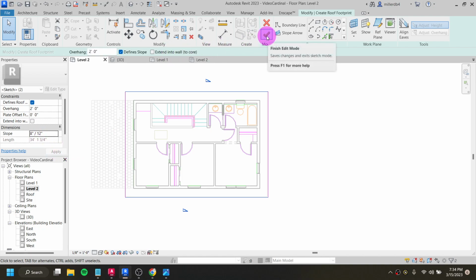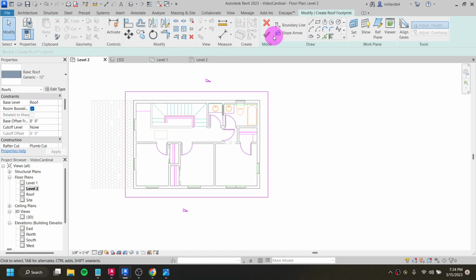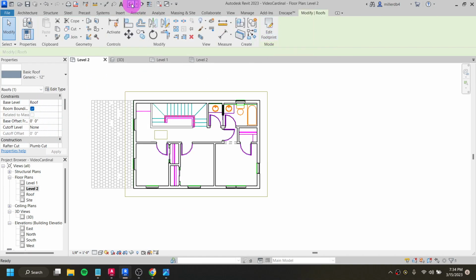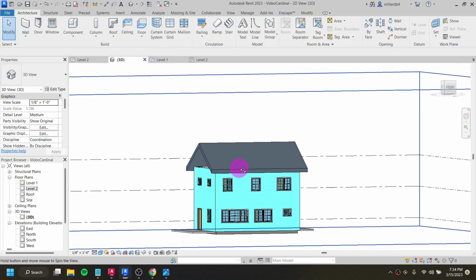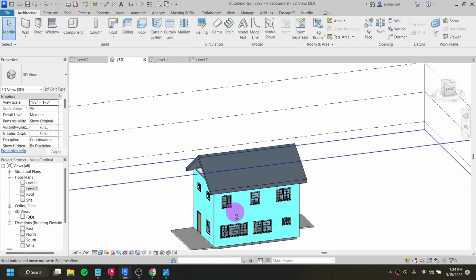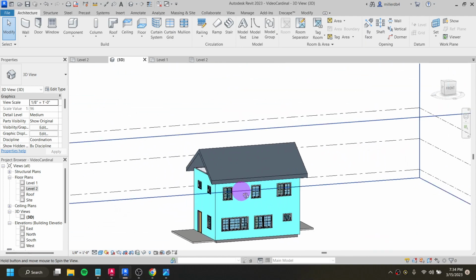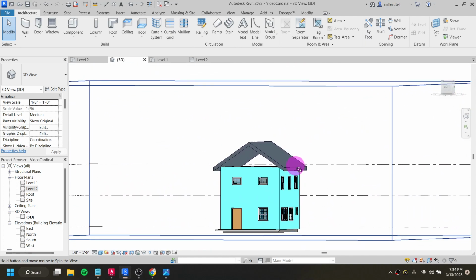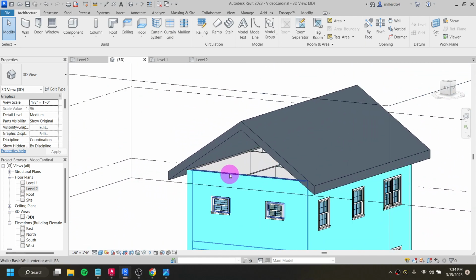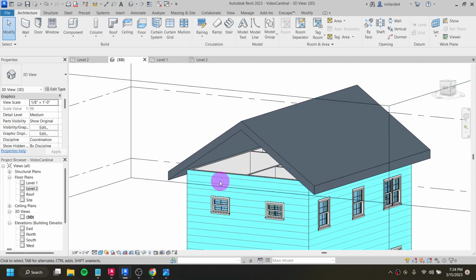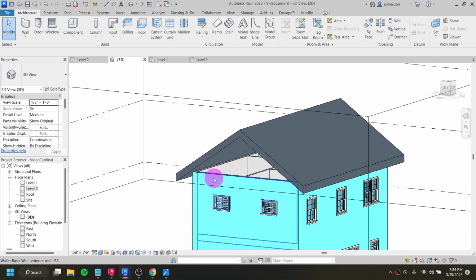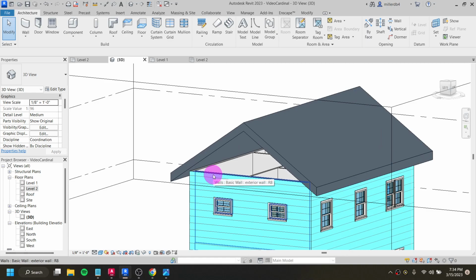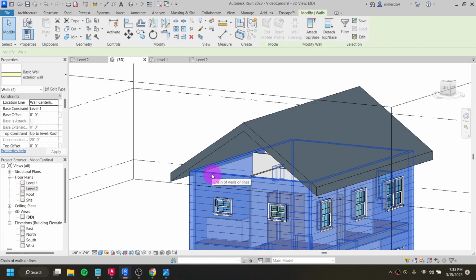Then let me just make sure that, okay, good, I've got my base level set to roof. I'll click OK, and I'll look at it 3-dimensionally, and now I have just this generic roof of a gable style with a 2-foot overhang. There is hopefully a problem that you guys are seeing here in the fact that there's a big old hole here. So all I'm going to do is hover over one of these exterior walls and hit tab so I get the chain and select them.